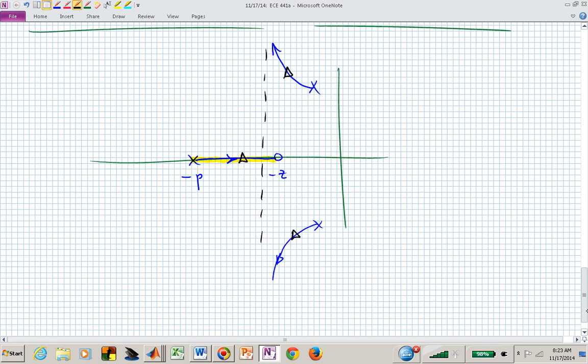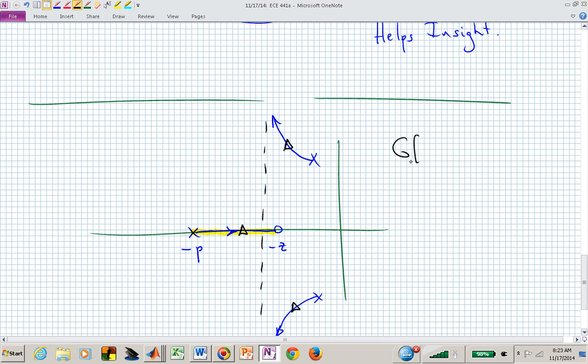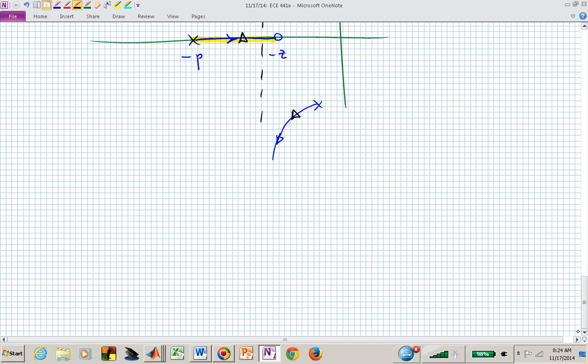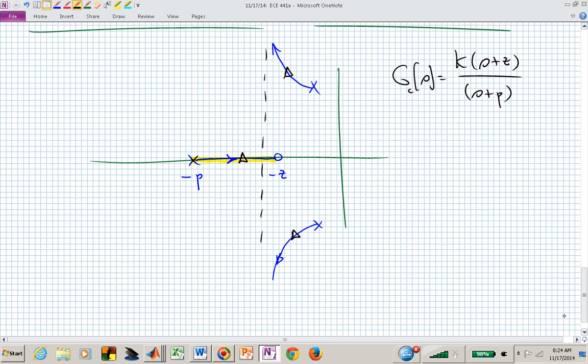Now, what we have then is this phase lead design that has some structure where the zero is closer to the imaginary axis than the pole. And we want to find our zero and pole location. We could do a lot of analysis, but maybe we want to speed this up by a certain amount. Let's just plop that zero down at -10, to try to pull that over.